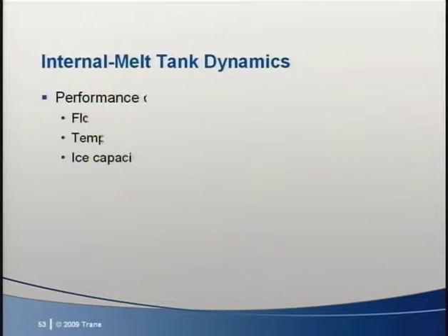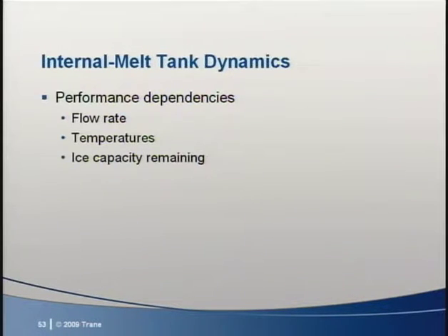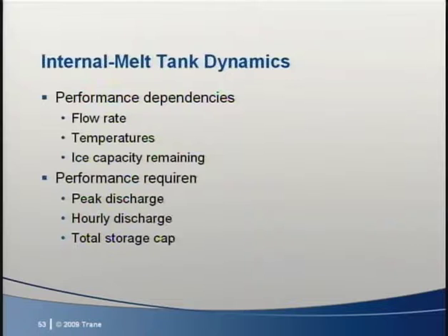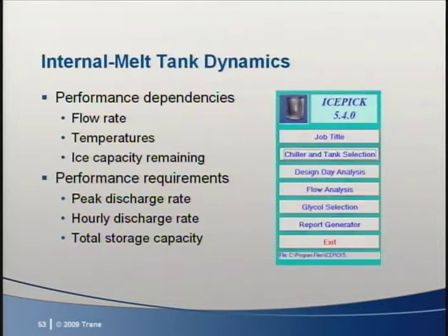Internal melt storage performance is not only dependent on flow rates and temperatures, but also on the amount of remaining ice. As loads vary throughout the design day and the ice inventory is gradually depleted, designers have to ensure that the chiller and storage equipment can provide adequate cooling capacity for all conditions. Manual selections are tedious, but computer selection programs make this necessary design step easy.